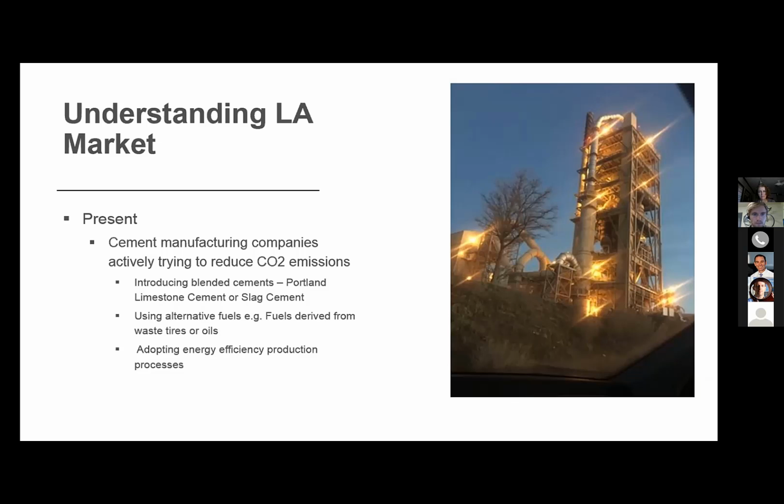But what we've seen in our R&D, and I'm sorry, I don't have a lot of data here, mine's more of a market summary, but we've run some R&D on these 1L13 cements with fly ashes and slag, and when you combine those materials, what we've seen at very high replacement rates of like 50%, we're actually exceeding the cement control, straight ordinary Portland cement control.